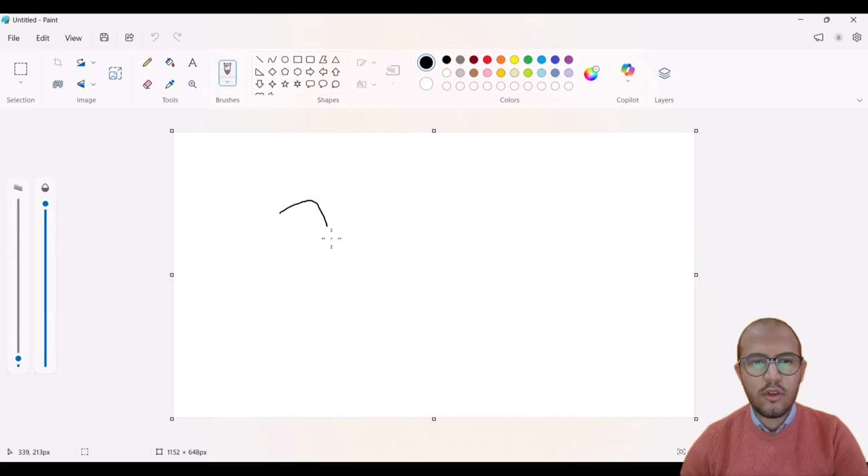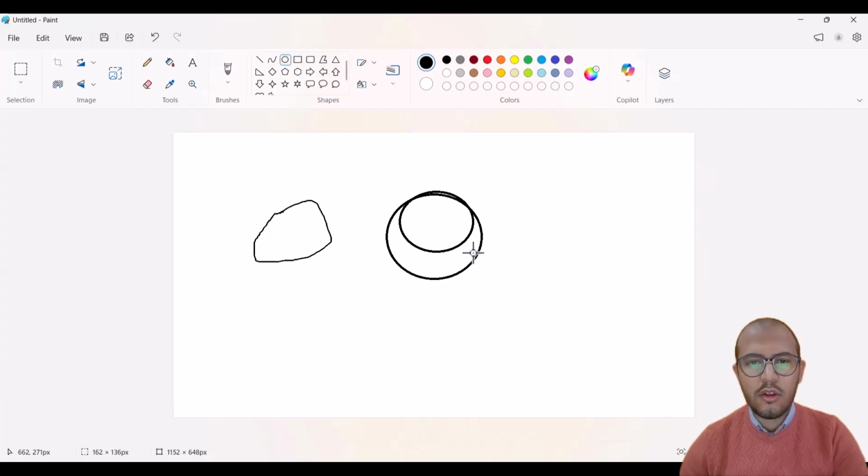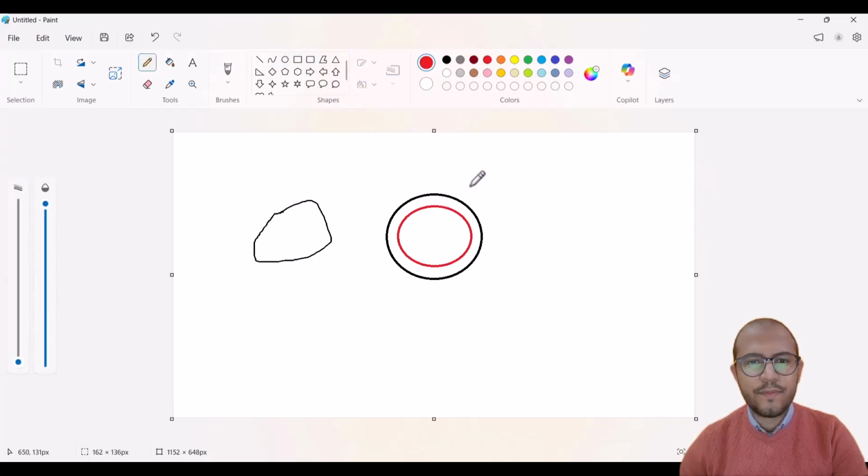I'm sorry for this circle. It's not a perfect circle, but we can use it as a circle. So this is the pipe. The pipe shape is a circle, and I'll make another one. This is the thickness of the pipe. We call this level the pipe crown, and the inner level here is the soffit. This level is the pipe soffit.